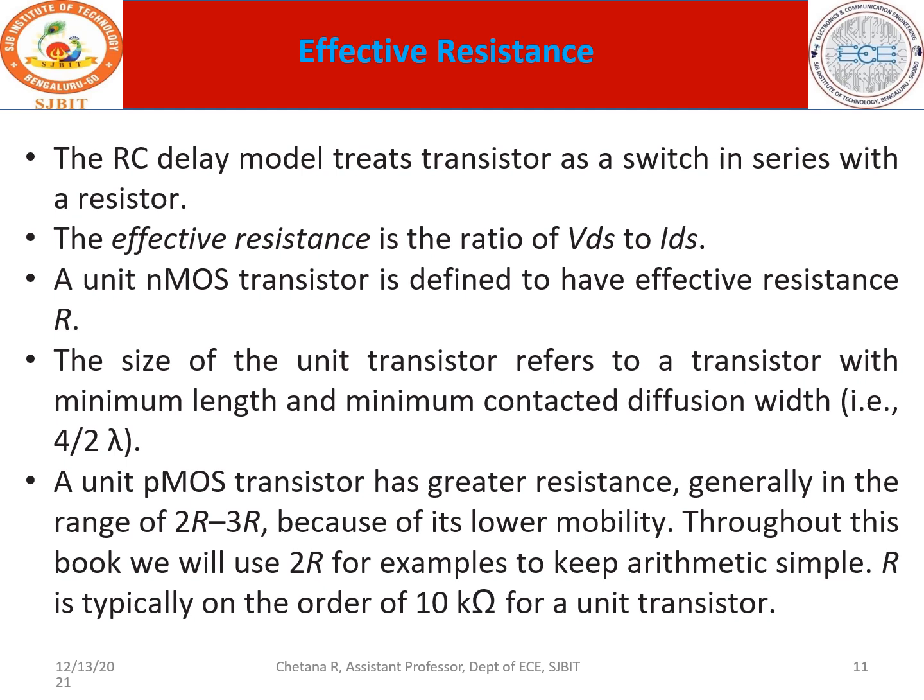One more thing, the R value of PMOS is more in terms of mobility. In PMOS, the width is normally made big because the mobility of holes is slow when you compare it to electrons. In order for them to move, if the space is very narrow, first of all the movement is slow and there is lesser speed.